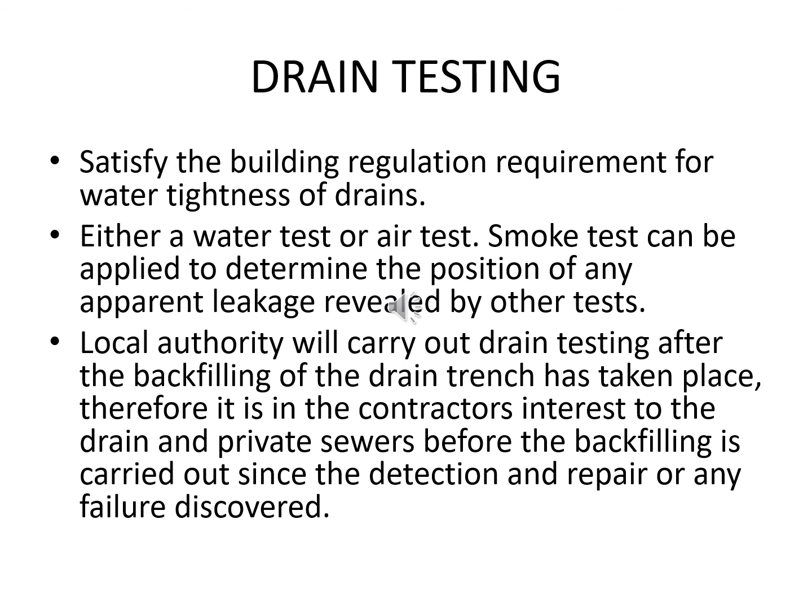A smoke test can be applied to determine the position of any apparent leakage revealed by other tests. Local authority will carry out drain testing after the backfilling of the drain trench has taken place. Therefore, it is in the contractor's interest to test the drain and private sewers before the backfilling is carried out, since this allows the detection and repair of any failure discovered.